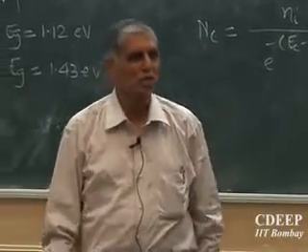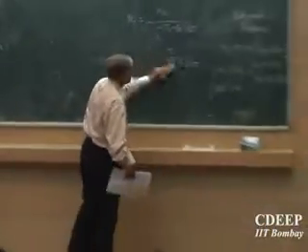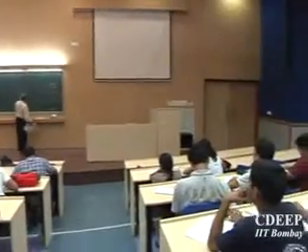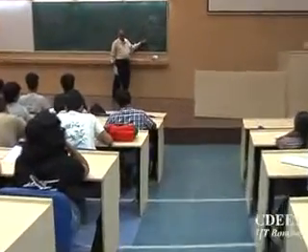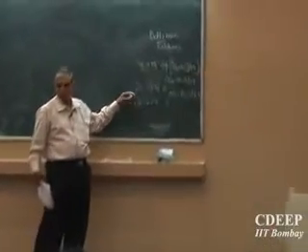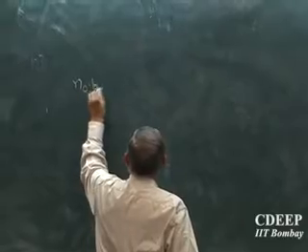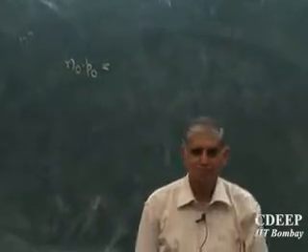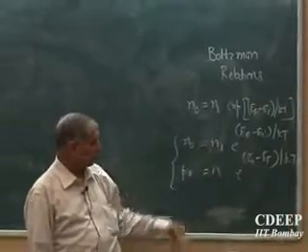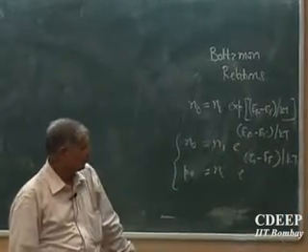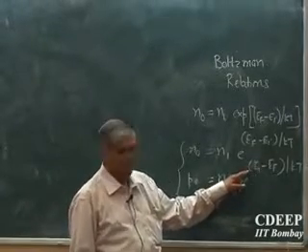Now this is very simple and very important for us because this relation is extremely interesting. These are not intrinsic values, these are only normal electron concentration and hole concentration. So now I multiply N0 and P0. What will happen if I multiply this? This will become NI square. What will cancel? Please remember, this is minus EF minus EI.